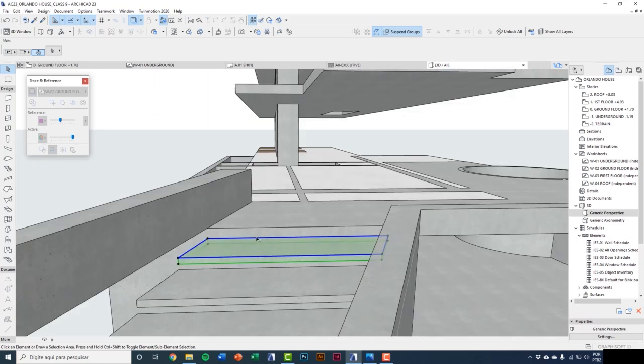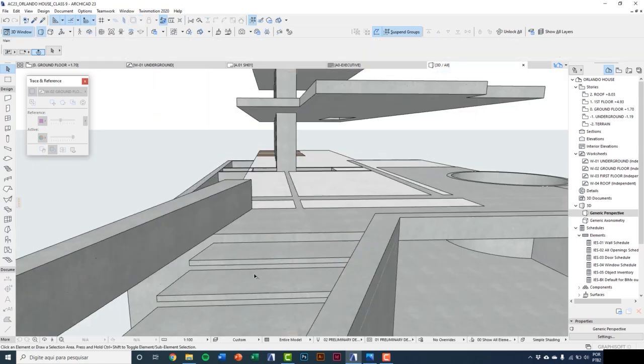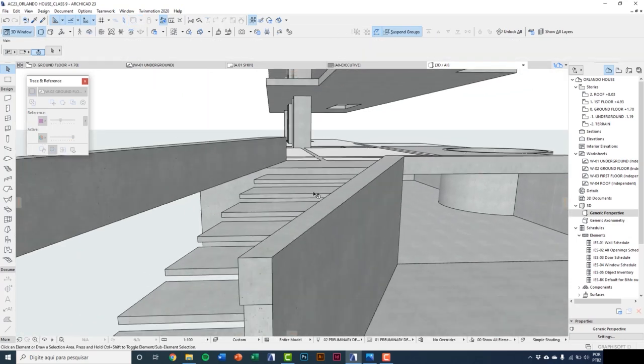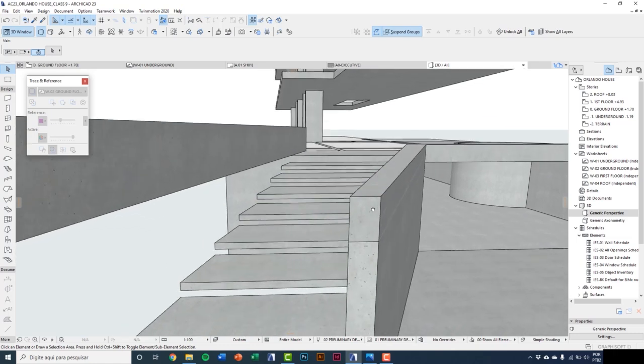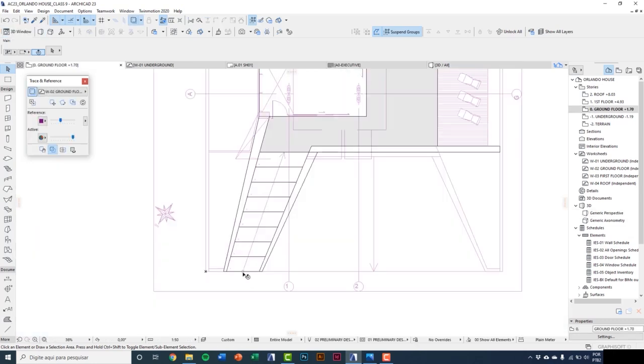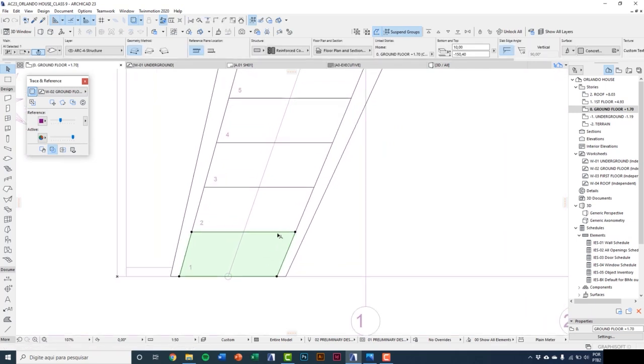In 3D, you see the stair, and as it is an untypical stair type, I'm doing with slab tool, but you're gonna learn about stair tool creating stairs inside the house later. Now we need to do a surpass of one tread over another, clicking on the edges on floor plan. I will do a 20 centimeters offset edge for each slab here.